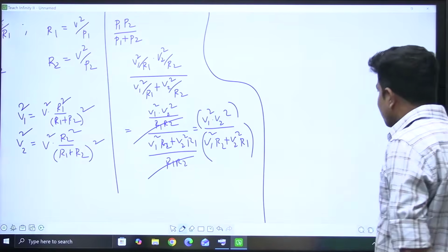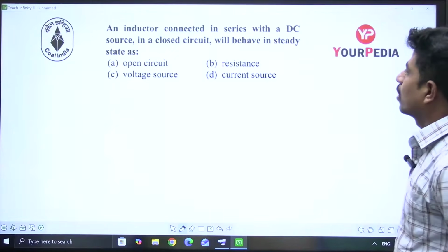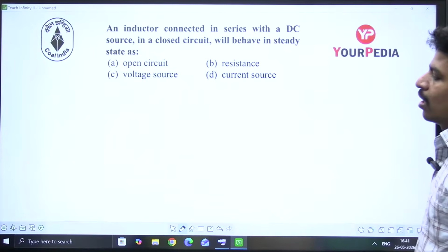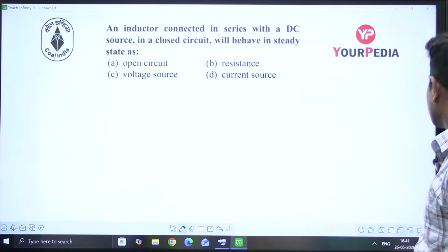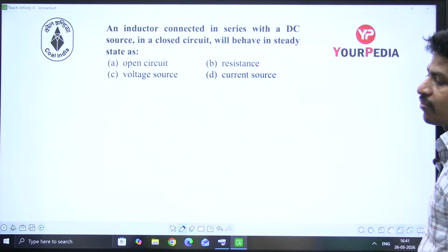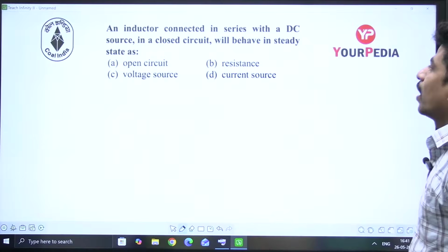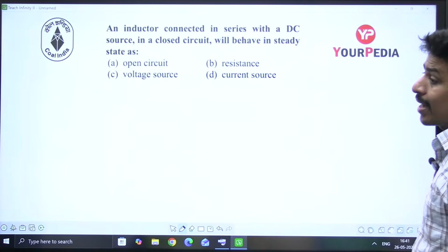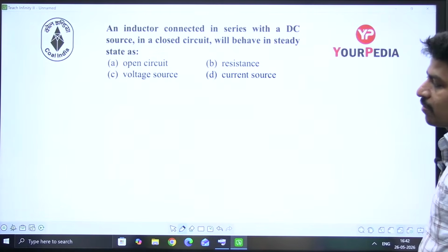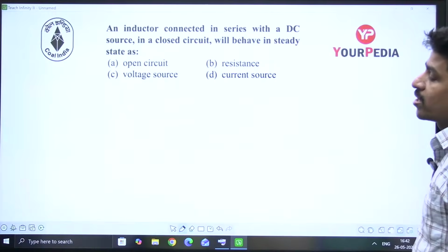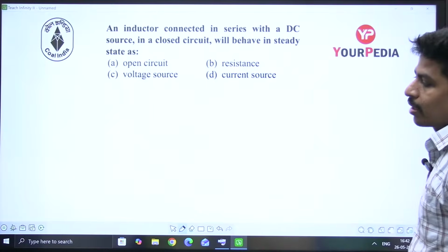Okay, let us skip that question for timing. Let's go to the next question. Generally that is a previously asked question. We, with this much experience, need not solve it in the exam, to the best of your knowledge. The only point here was that the question gave P1 and P2 as the rated powers. Rated powers means when you apply the full voltage V, then that power. So P1 is equal to V square by R1, not V1 square by R1. Okay, that is the point.